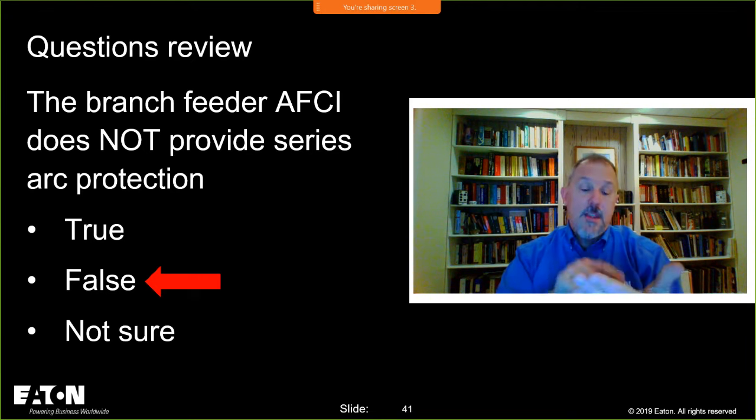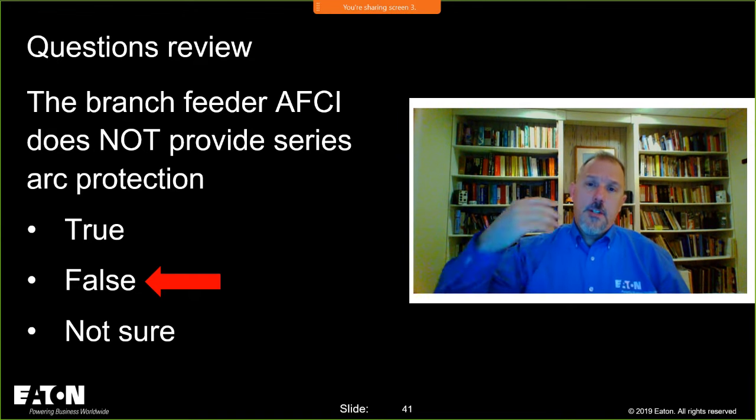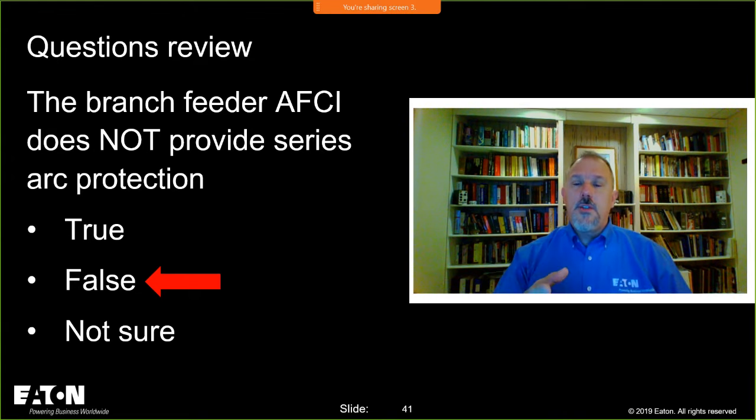So you can't simply put a handle tie on your breakers. You have to look at the breaker and see, is it rated 120 or is it rated 240/120 or 120/240? What is the rating of that breaker? If it's slash rated, then you can put a handle tie on it. If it's not slash rated, you cannot. Always go back to the rating, and then also call the manufacturer and help them understand what you're trying to do with that product and make sure it's legal before you get an inspector out there who's going to go, you're out. So that's an important thing to remember.